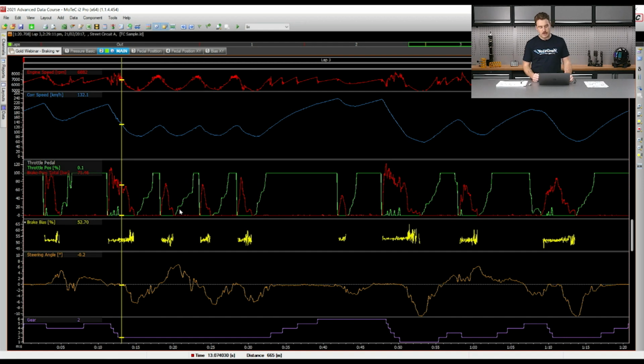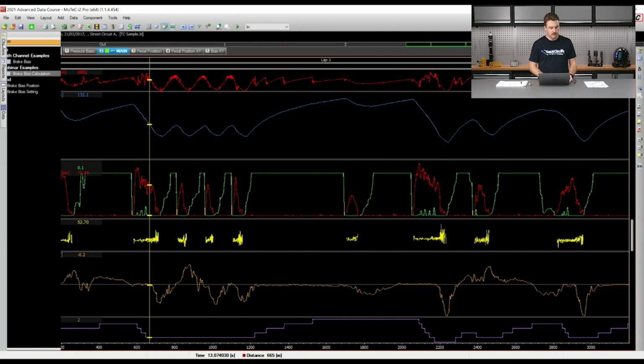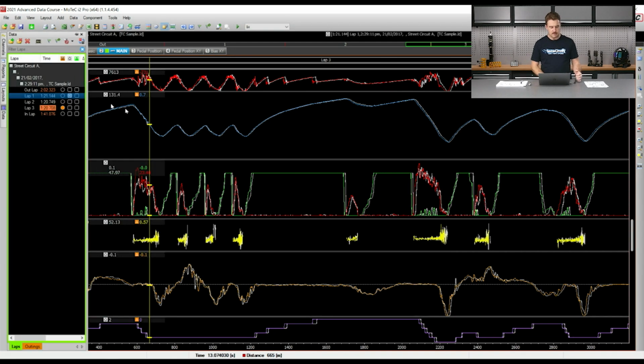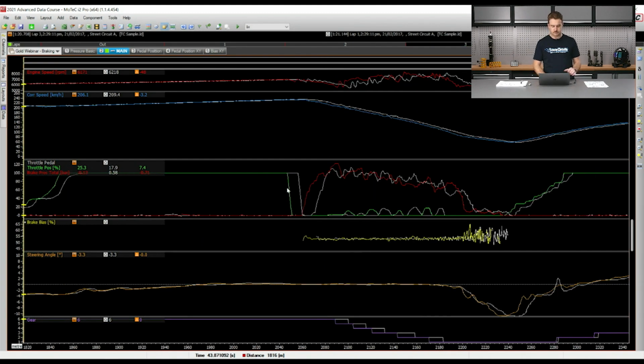So as I said, one of the ways you're often using brake pressure data is to understand when on track, but also with how much intensity the driver is actually braking. So let's add an overlay in here. I'm just going to use a different lap as an example, even though this is from the same driver. But for argument's sake, let's look at a place on track where we have a difference in the braking marker. And I can see down here, looks like there's a difference.